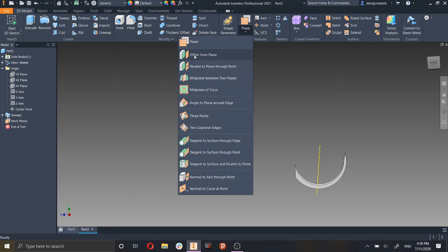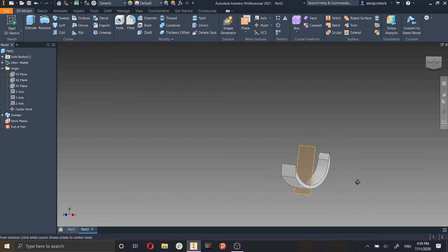You can also do a plane that is offset from another plane. So if I offset this from this plane, for instance, I can choose how much distance I want it from. I can choose what units I want it from as well. I mentioned in the last video, 2 cm if I want it, like 2 centimeters. It'll obviously default to inches backward. It'll become inches when you, let me show you another tool.